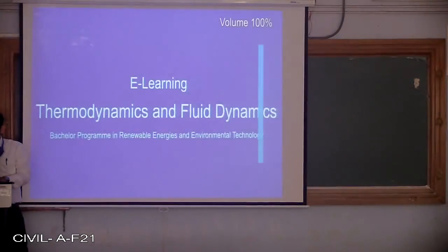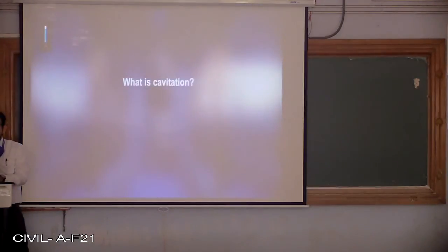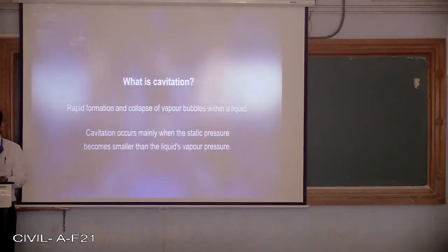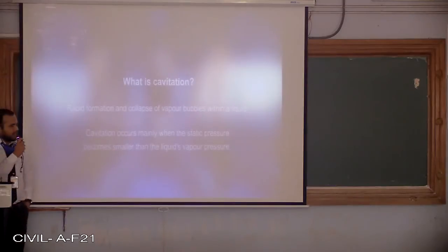Welcome to e-learning in thermodynamics and fluid dynamics of our bachelor program in renewable energy and environmental technology. In this series, we are going over the phenomenon of cavitation in water and its consequences. What is cavitation? Cavitation is the rapid formation and collapse of vapor bubbles within a liquid. Such cavitation bubbles are formed mainly in locations within the liquid where the static pressure becomes smaller than the liquid's vapor pressure. I hope you have studied what vapor pressure is. I won't repeat it and waste time now. I have studied this already in fluid mechanics.